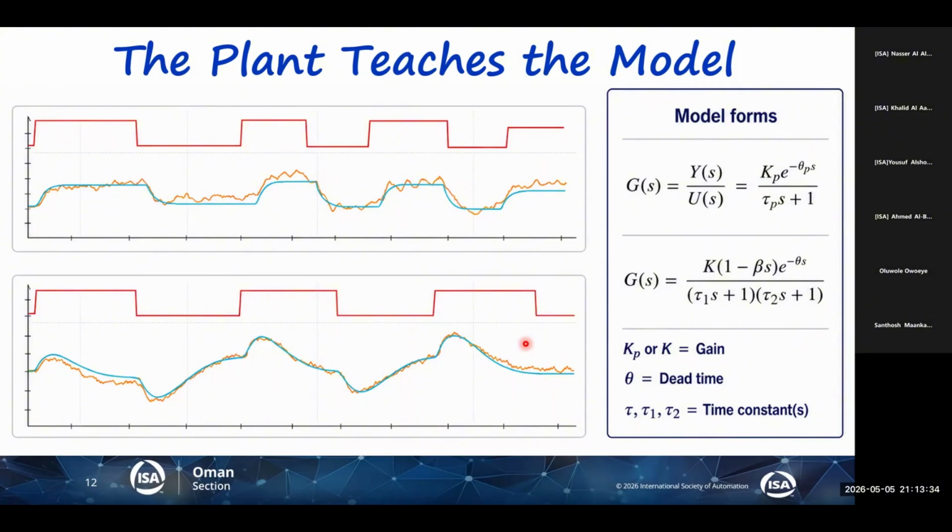After that, you'll go to controller design, where you will design the controller. You will run simulations for all the cases, for all the scenarios. If in the design workshop you say CV1 should be within this range, it's more important, CV3 should be within another range, it's less important. You should create conflicts. You start with the base case where everyone is happy, every CV is happy, and then you start creating conflicts.